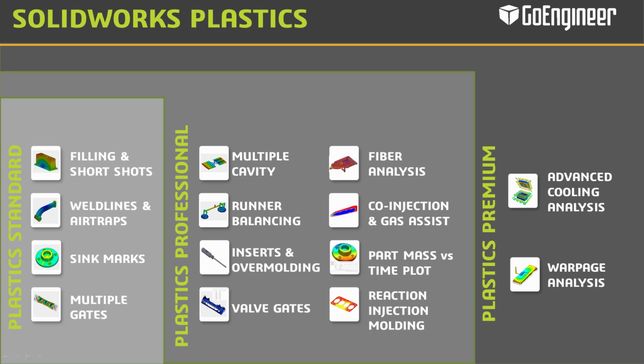It will also do valve gating, so you can have multiple valve gates on a hot runner system, and it will actually do automatic valve gate timing, which is really nice as well. So you get a plot that comes out showing the timing at which the valve gates open.